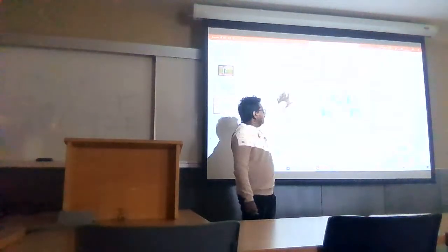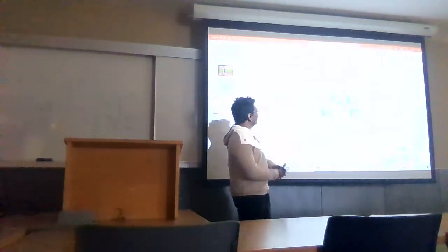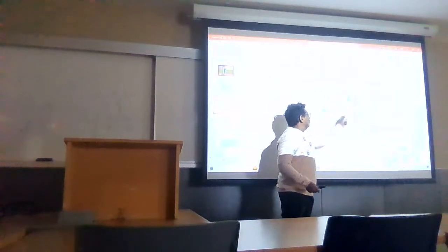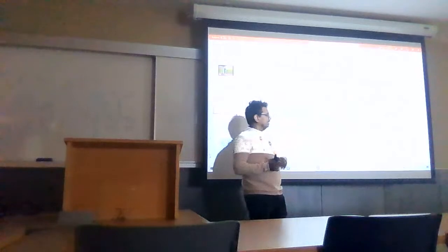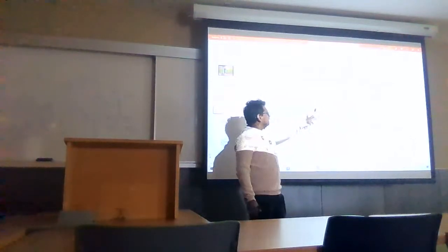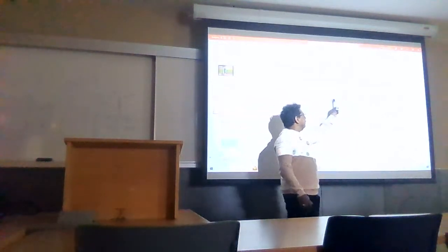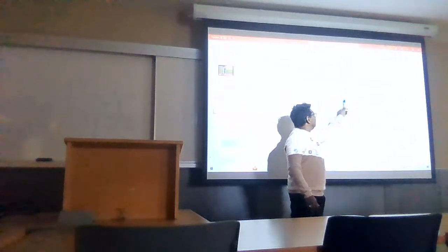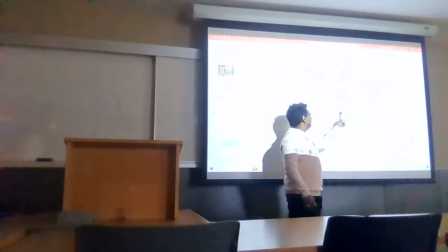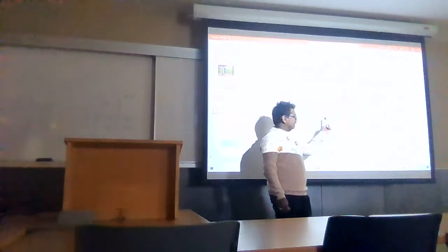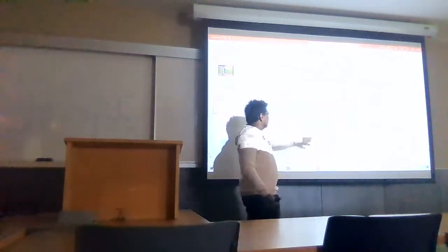If it is a current mirror, you can see there are 4 blue devices and 4 red devices. So there is some common matching, let's say A, B, B, A, B, A, A, B. This is a matching, and you can see there is no mismatch.